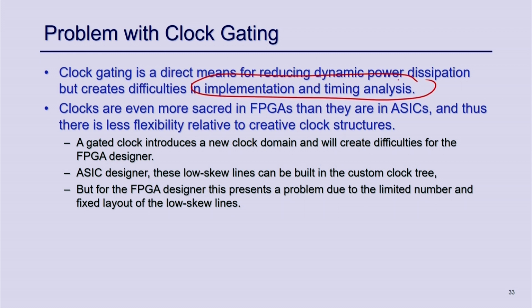Specifically for FPGA, we have only one master clock line. So, if you have multiple clocks, they will be routed through the normal LUT structure, and that will create a lot of delay and a lot of problems. So, multiple clock domains are not a practice for an FPGA target, specifically this gated clock. So, that may not be feasible in an FPGA target, right.